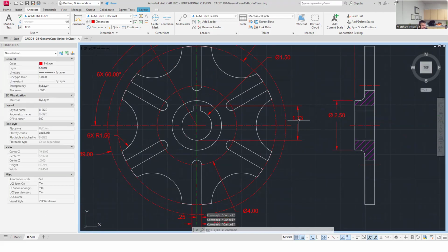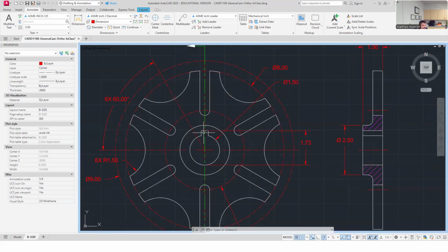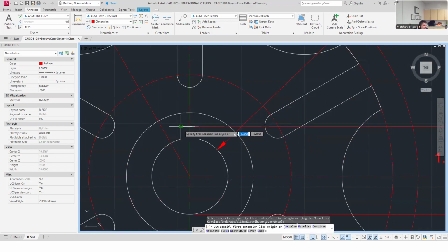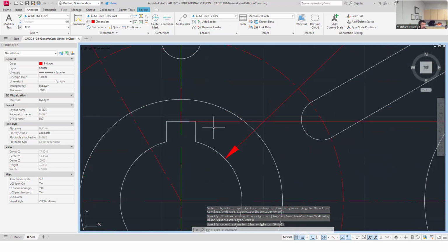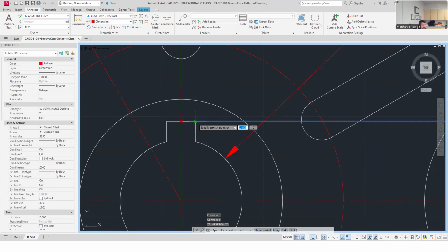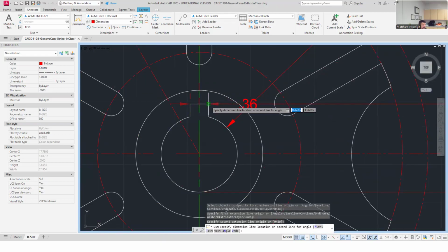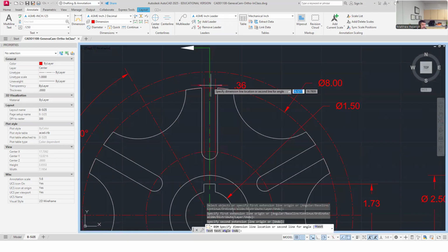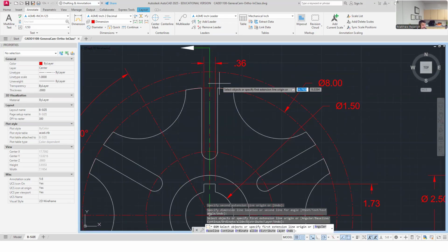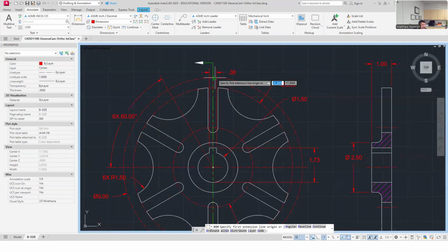So there's one way that we size a keyway. The other way we size it is this way and across, and then how far off center it would be, even though sometimes the off center is dropped because it's understood. I'm still going to put it just for our size and locating mentality here. So it's going to be a dimension of its overall width here, and I can tell that I've got to pull this one back. This one should come to this object edge, just based off how I pulled that. But here's my dimension now for its overall width, 0.36. I'm going to pull it above and beyond, probably out here. I'm probably going to have to move that cutting plane line as well.